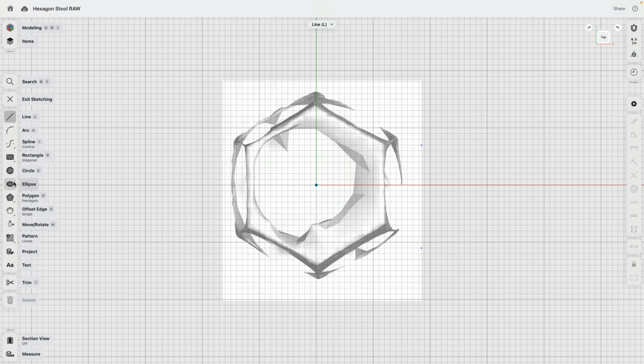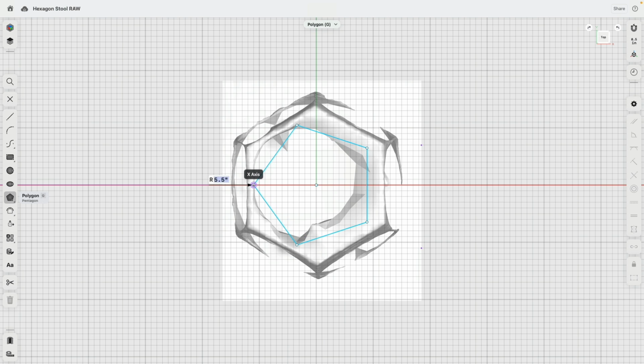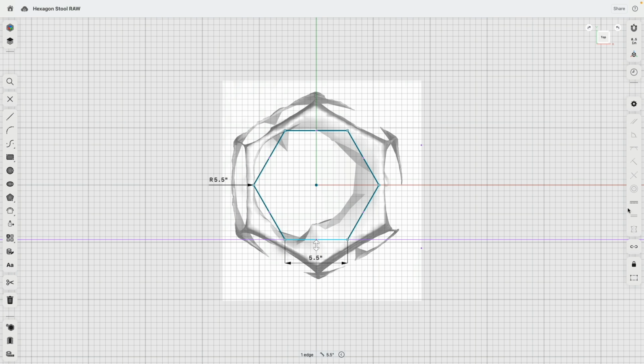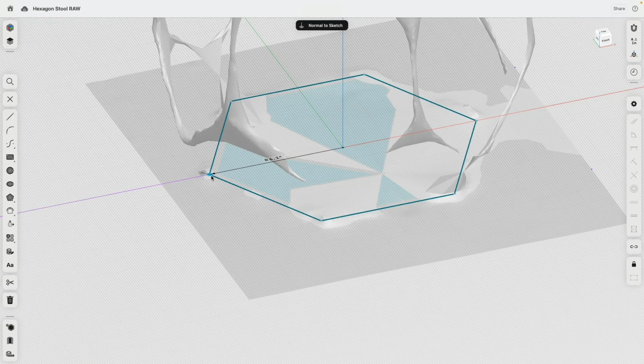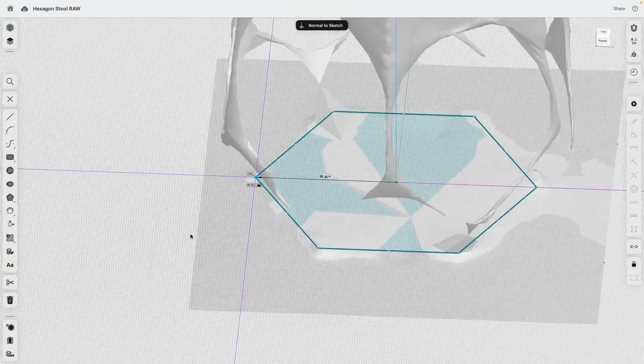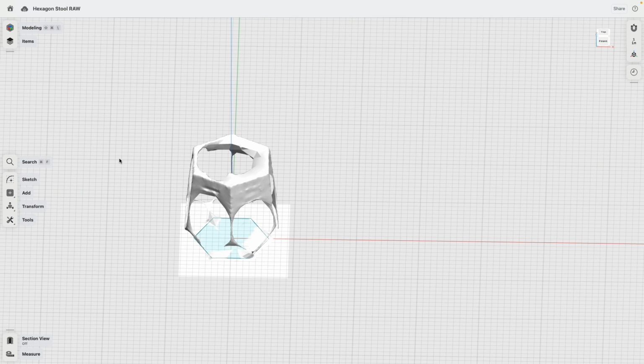So let's get started. We go to sketch, in top view, go to polygon. From the center, we drag this one out 5.5 inches. That's good. Click. Then we go to sides, enter 6, and press escape, so we stop the polygon drawing command. Then I can select one edge here and make sure this is horizontal. Now I can adjust the size of this hexagon, and there you see, this is getting very close, or maybe it's 6 inches. Okay, sketch number 1 is done.